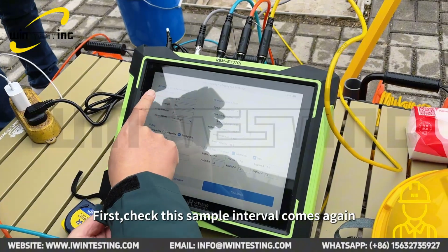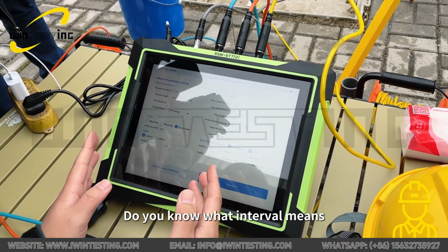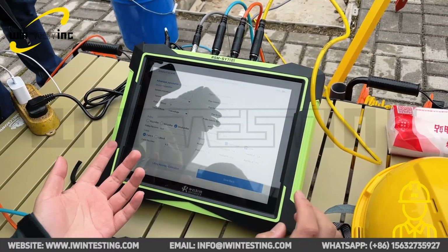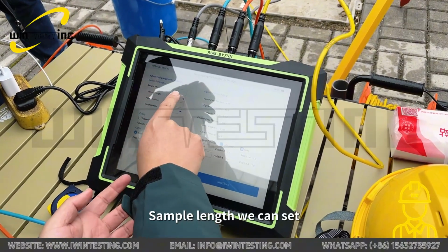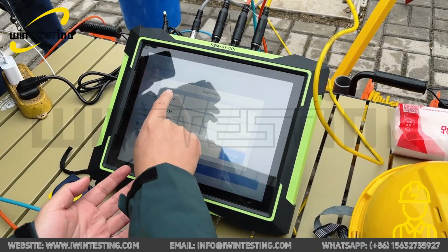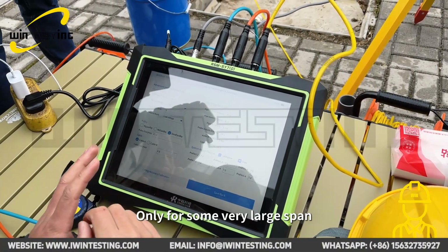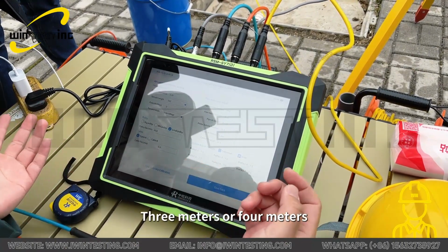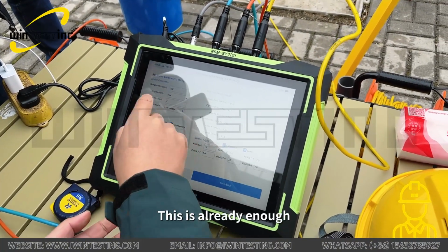Okay, first check this sample interval. Interval comes again. So, do you know what interval means? We have a waveform with many points, and the distance between two points is the interval. Here we can set the sample length to 512 or 1024. Sometimes we need to input it manually, only for some very large span, like 3 meters or 4 meters. Most of the time we don't need to change it. It's already very enough.